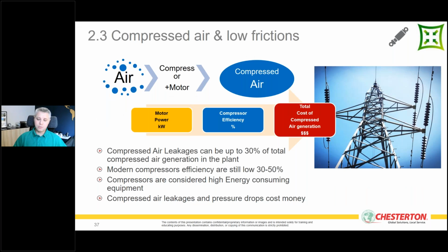So first of all, let's have a look at pneumatics. In this case, I have a pneumatic cylinder here with me. If you are operating such a system, to be able to use pneumatics, you need to provide this kind of energy first. So you need to have compressed air. How do we make compressed air? We take air from the atmosphere and we use a compressor.